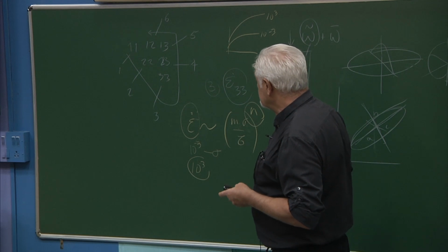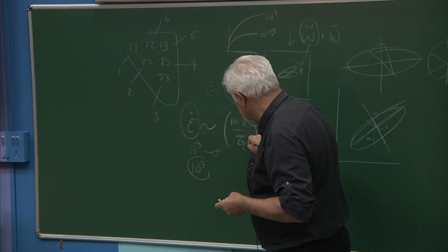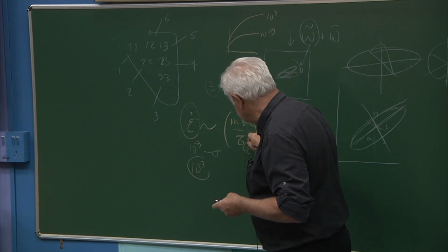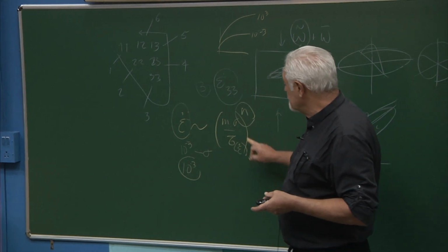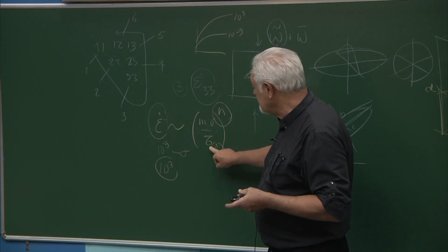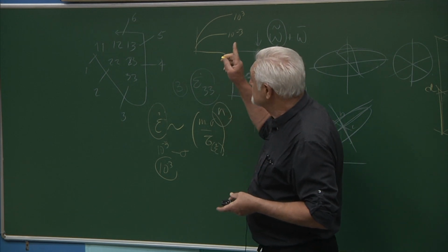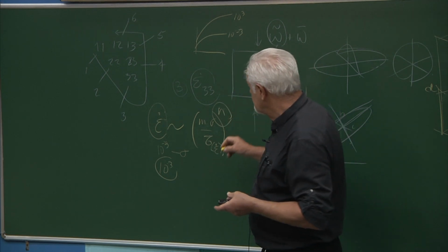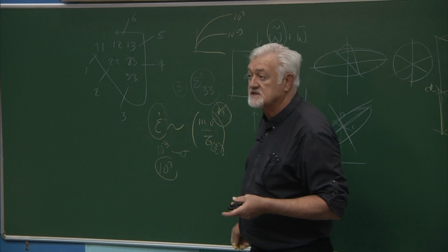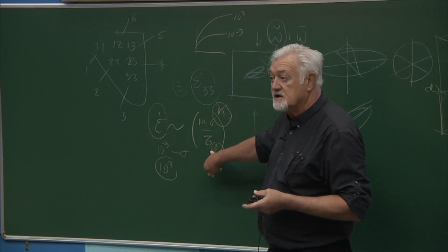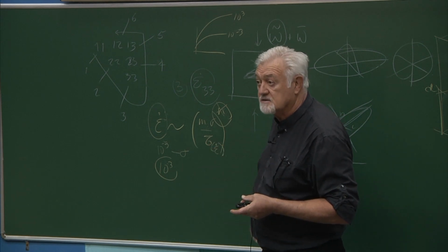Now, in general, you will leave that on, but if this tau, because your constitutive law is more complex, is a function of the strain rate, you don't want to have two effects, one coming from here and the other coming from here. So if you use rate sensitivity equal to 0, it eliminates the effect that is coming from this value n, essentially. And it uses the rate dependence that you put in the parameter tau.